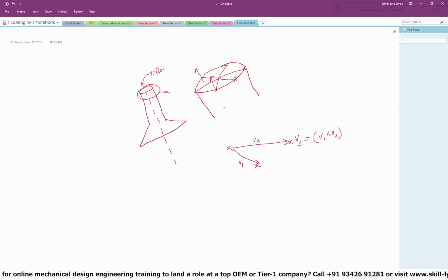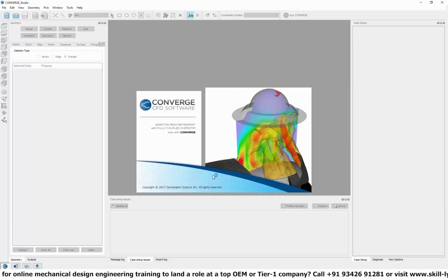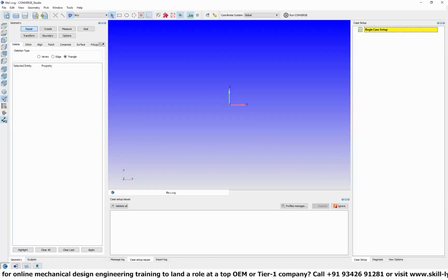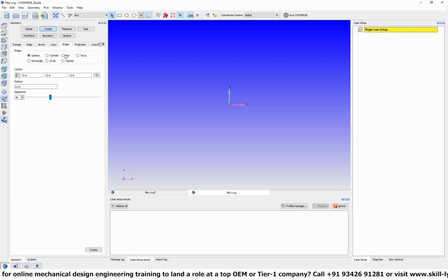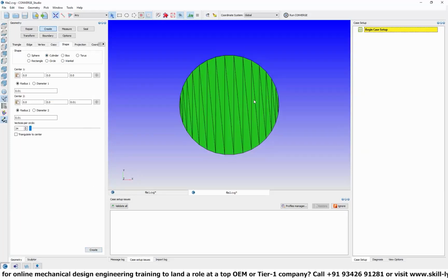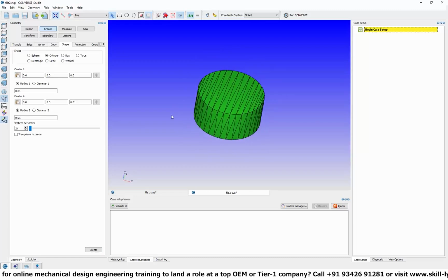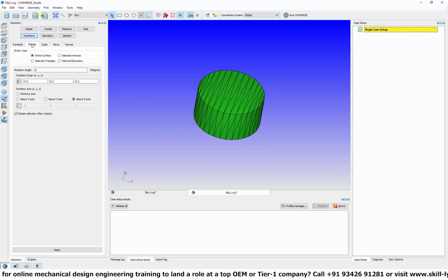That is why in the videos you see me measuring the arc, because that helps me compute the center of the arc and also the arc normal. Now the center of the arc is extremely useful when we are trying to rotate the geometry. For example, let us take a look at this simple cylinder. Let us say that I want to rotate the cylinder about the z-axis. When I transform, rotate, about a particular axis, the z-axis, then I need to specify the origin.